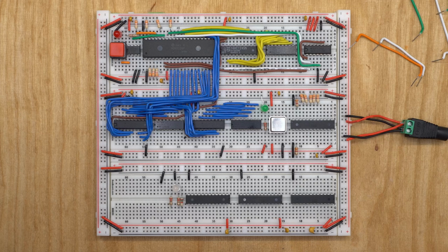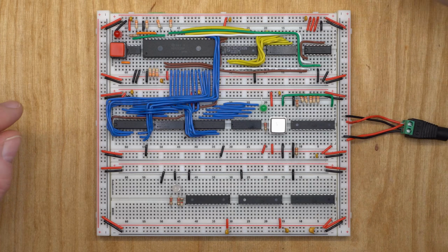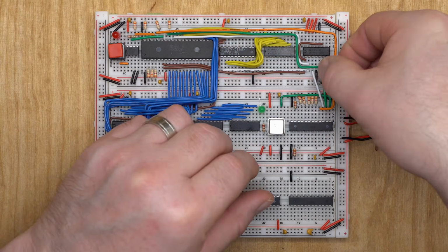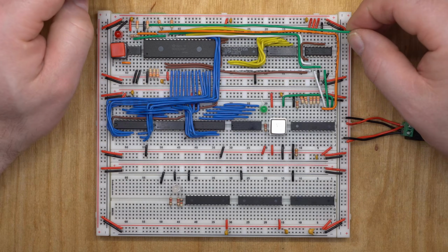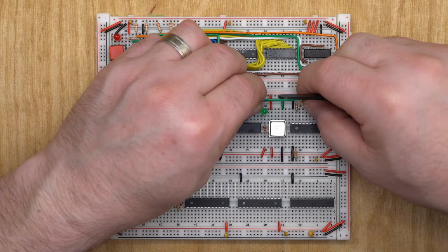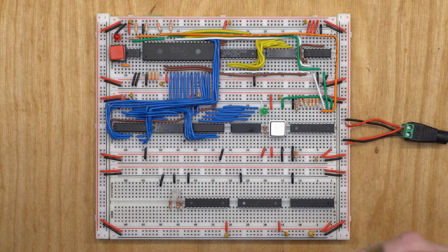At this point, ground and VCC are wired, decoupling capacitors are in place, and a few resistors are installed on the wait state generator PLD. Time to wire the new logic. The oscillator output goes to pin 1 of wait state gen, buffered E goes to pin 2, buffered read-write goes to pin 3, reset from the CPU goes to pin 4. The oscillator also feeds to pin 38 of the CPU, which is its clock input, because the CPU does enjoy knowing what time it is.